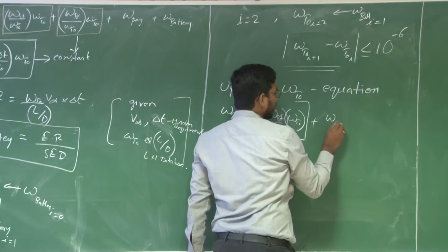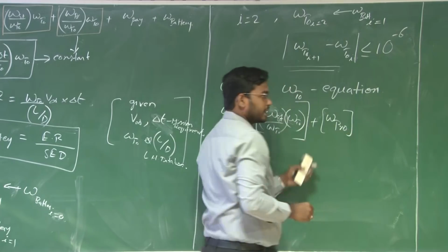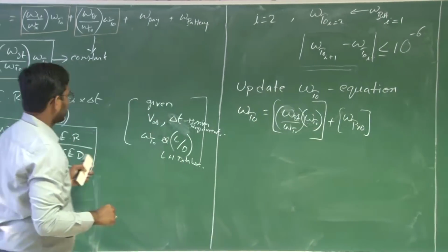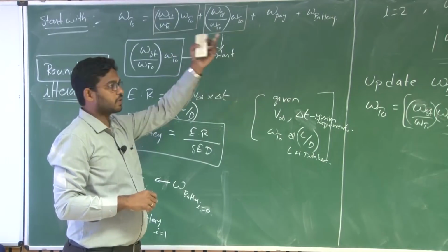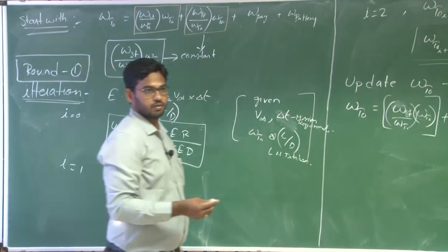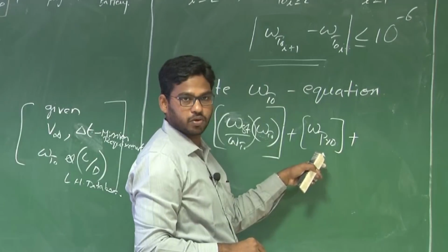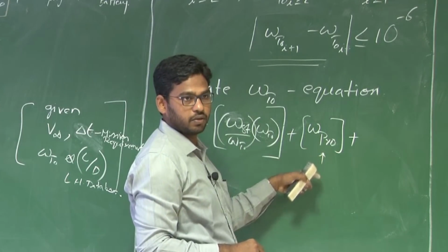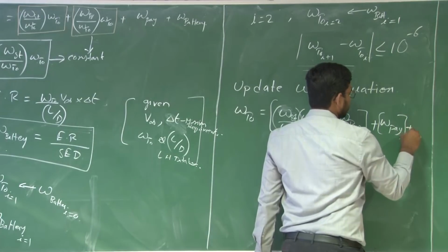And you have the propulsion weight here. So propulsion weight can be readily considered as an input. Why? Because you are actually selecting a power plant, and the details of the weight of that power plant are available from the manufacturer, right? So this is not an estimate anymore; it is an accurate value. Payload is also an accurate value that you will consider, plus battery.